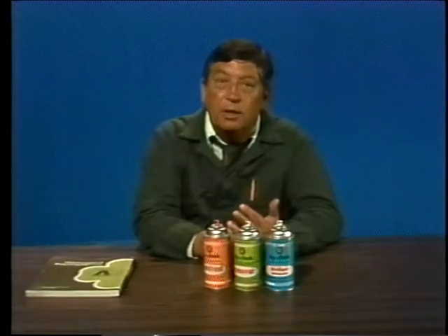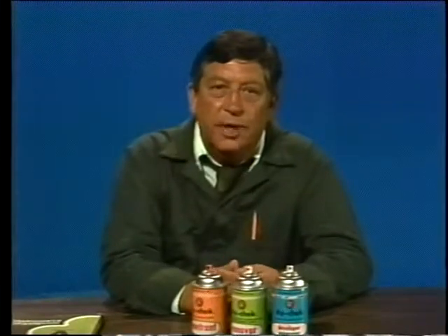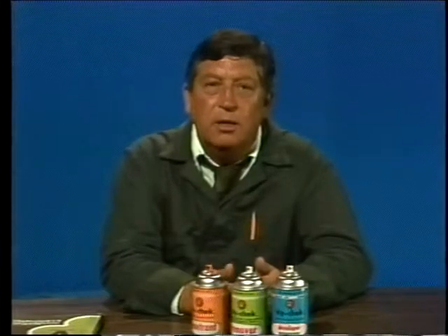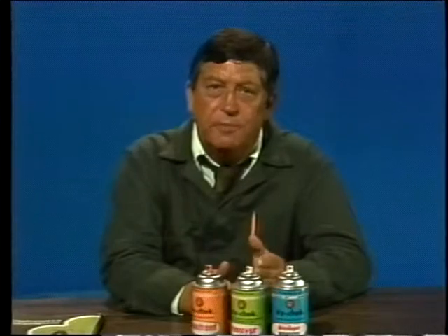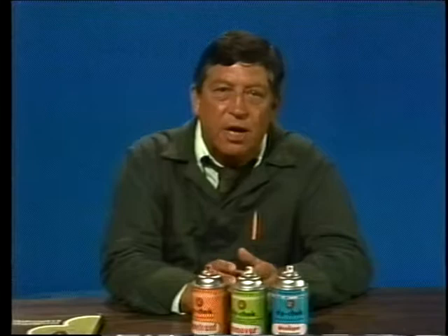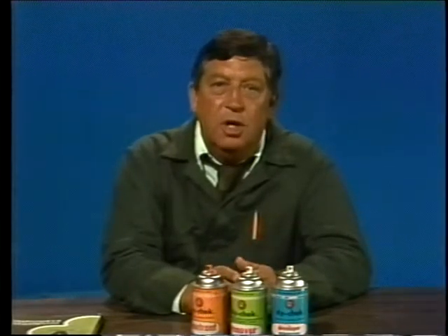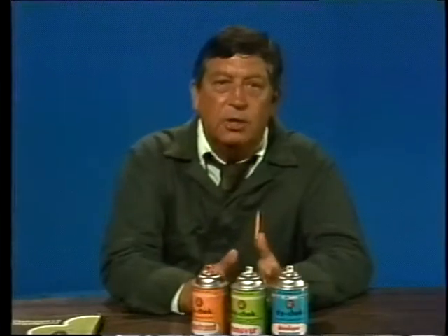The liquid penetrant test is commonly used because it's quick and easy to perform. This test, however, has some important limitations. For one, the dye only reveals surface flaws. It doesn't give any indication of any defects inside the part. Two, this test is only effective on finished surfaces. A raw casting is too porous. The penetrant would seep down into the pits on the surface. That makes it pretty hard to interpret results. The whole piece would look like an indication.